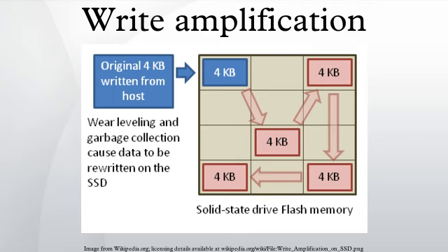at the same time. Unfortunately, the process to evenly distribute writes requires data previously written and not changing to be moved, so that data which are changing more frequently can be written into those blocks. Each time data are relocated without being changed by the host system, this increases the write amplification and thus reduces the life of the flash memory. The key is to find an optimum algorithm which maximizes them both.